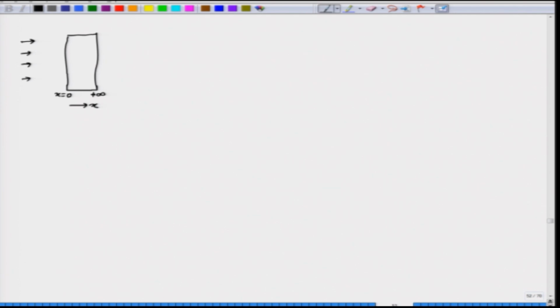The heat treatment is usually carried out and the atmosphere is maintained such that there is a constant carbon concentration at the surface. At the surface, let us denote the concentration by Cs, and typically steel will have a certain carbon concentration to start with. To make the problem simple initially, let us assume the carbon concentration in the steel before carburizing is 0, and since we are maintaining infinite boundary conditions, at the other end the carbon concentration will always remain C0.